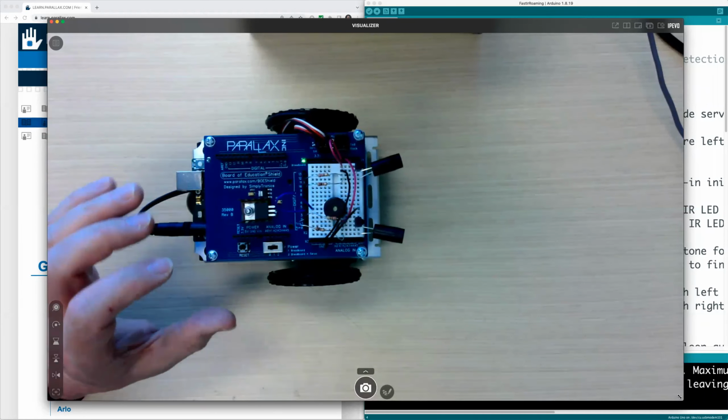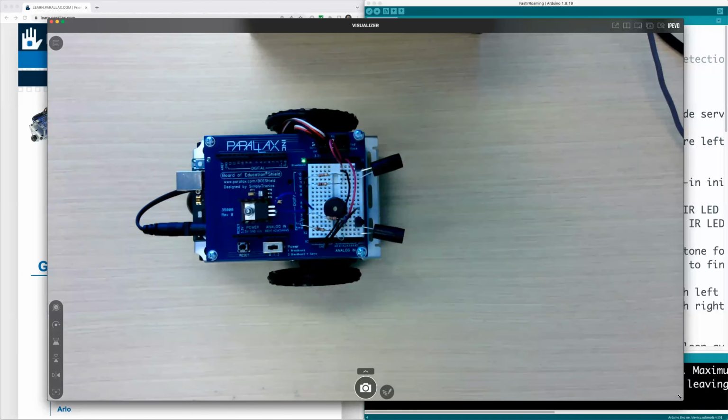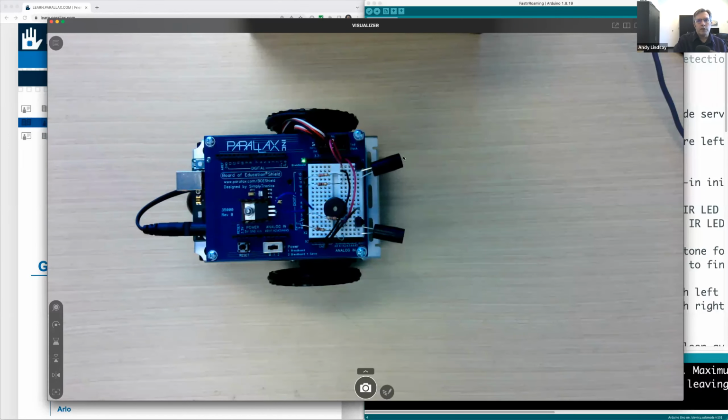We have an observation that the problem with the whiskers is the height. Oh, yeah. If you have something that's below whisker height, the whiskers won't touch it. That often leads to discussions, robotics-wise, about redundant subsystems. Some of the other things that we've noticed is that ultrasonic detectors don't work very well on teddy bears because they muffle the ultrasonic pulse, and so it can't bounce back to the receiver.